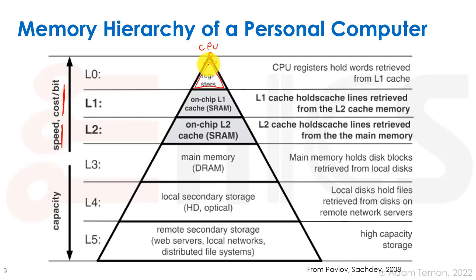memory that we have. Usually the first level of a cache or the closest memory, the tightly coupled memories and so forth, will be made with SRAM, which is an embedded memory, an on-chip type of memory, which we have been learning about in this lecture. So we have 1, maybe 2, maybe 3 levels of cache or some other scratchpad memory or some type of memory on chip that is made with SRAM. And again, SRAM is going to be 6 transistors per bit, so it's more costly than other things, but it's less costly than the registers, which are really a few dozen transistors per bit. But it's also going to be slower.